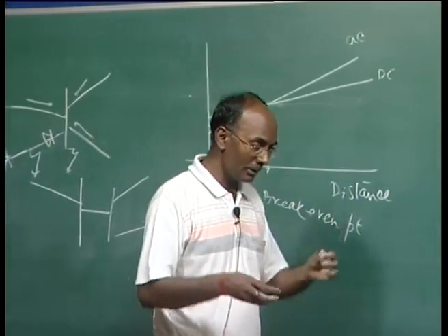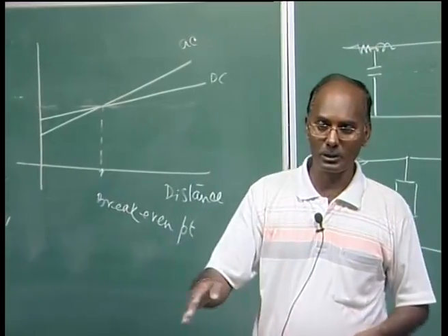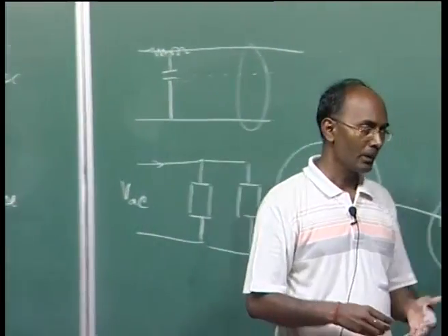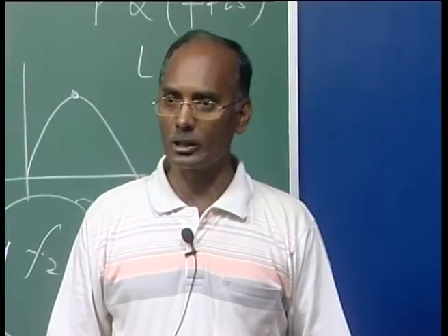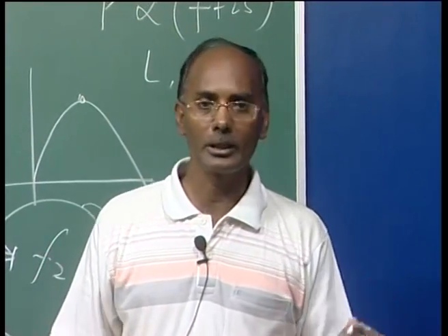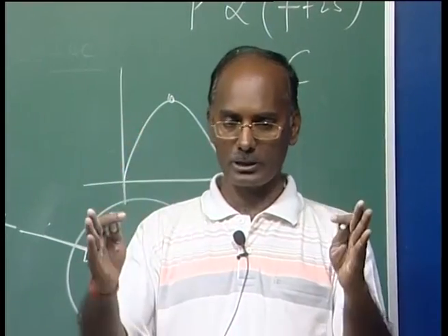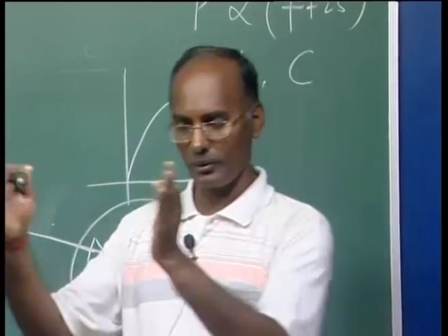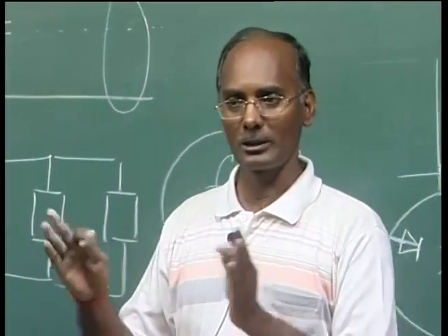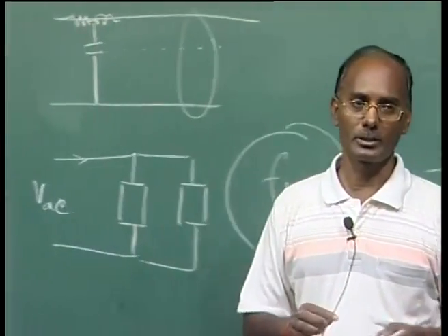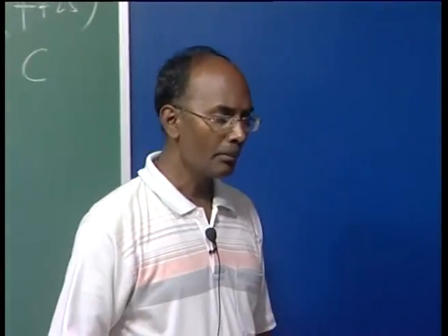Now the cost is not so expensive, because of the advancement in power electronic devices. The cost is going to reduce, no doubt, but it is still higher compared to AC. If you compare an AC substation with a DC substation of the same rating, you will find the DC substation costs more. But we hope that in future the cost will keep reducing due to advancement in power electronics technology, and let us see in the future. Another concern is the introduction of harmonics.